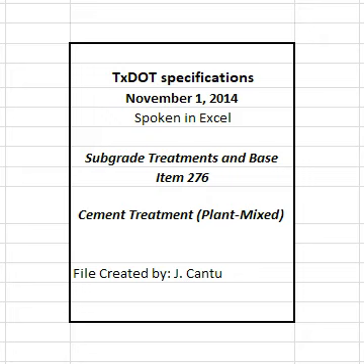6.1.2.2 Thickness deficiency greater than 1.0 inches. Remove and replace areas of treated base found deficient in thickness by more than 1.0 inches, unless otherwise approved. Take exploratory measurements at 50 feet intervals parallel to the centerline in each direction from the deficient measurement until a measurement is not deficient by more than 1.0 inches. The minimum limit of non-pay will be 100 feet.